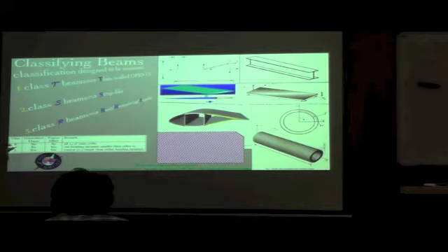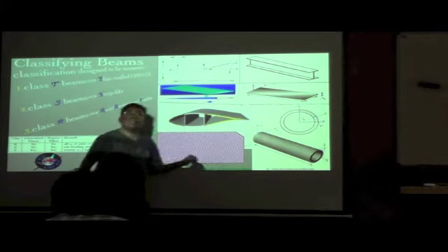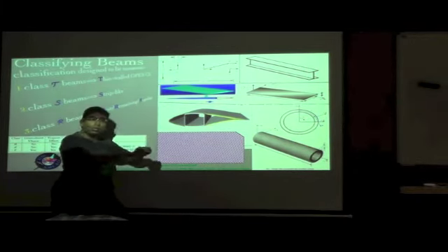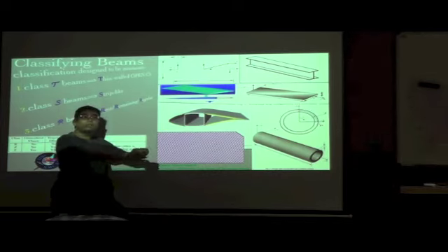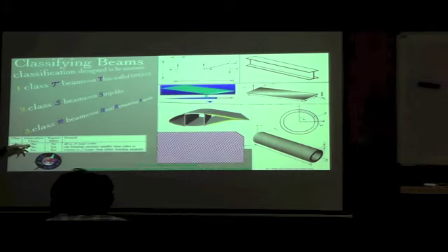So now these are the three classes of beams: class R, class S, and class T. If you look at class R, that is the simplest as far as torsion is concerned, because the torsional stiffness for these beams is fairly large, and therefore the torsional curvature, or the twist per unit length, is pretty small. It's a higher order term, and therefore neither the Vlasov effect, kappa 1 prime, nor kappa 1 higher power effects will be important there.